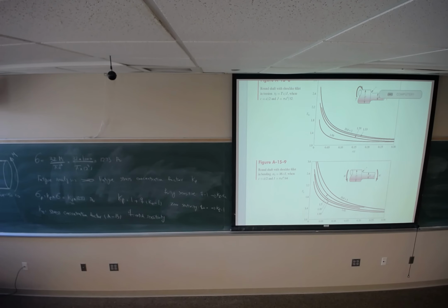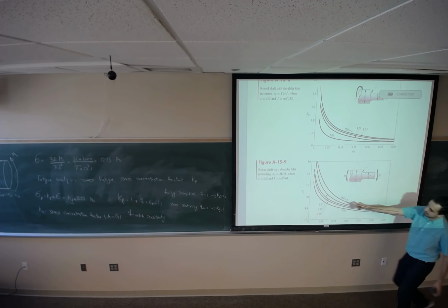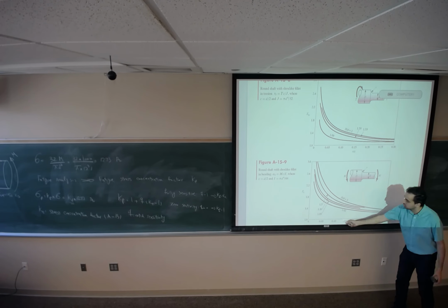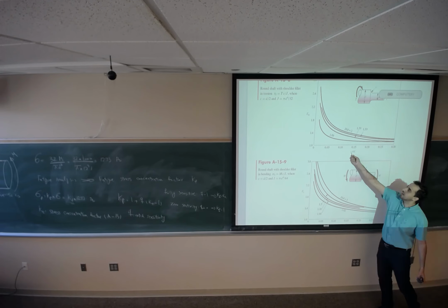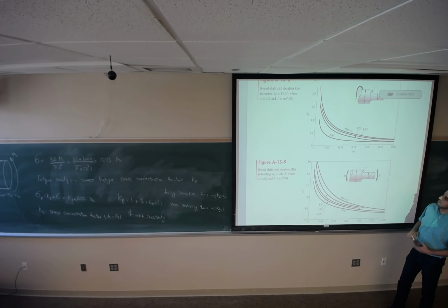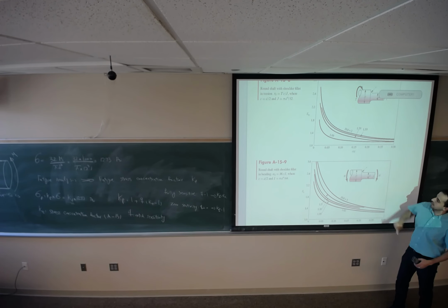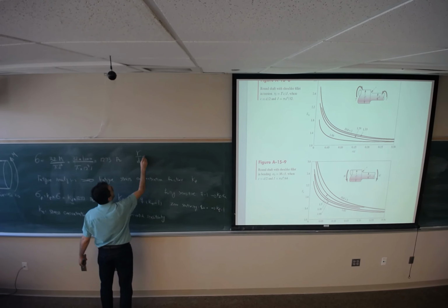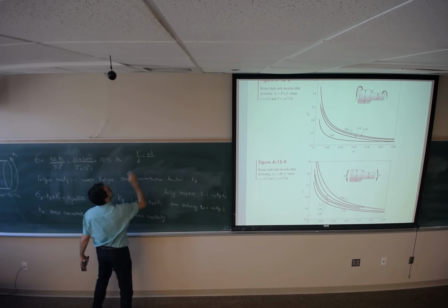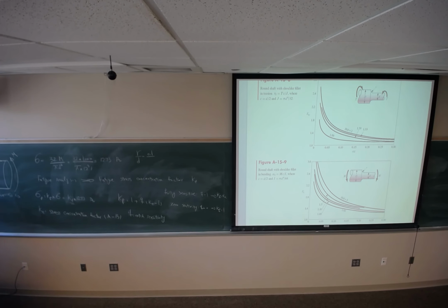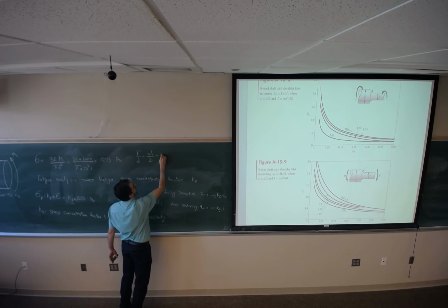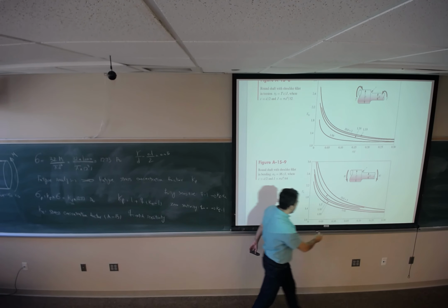For this one, you can read the value for Kt. To find Kt, first you need to find r, the radius of the fillet, divided by the diameter of the smaller component. So r divided by the smaller diameter is 0.1 divided by 2 inch, which is 0.05. So 0.05 is going to be somewhere here.